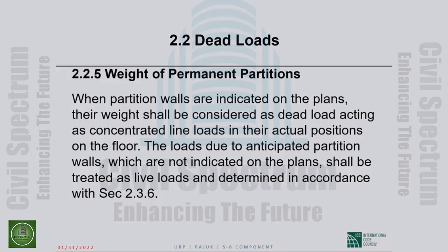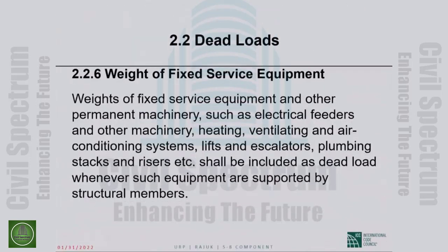The load factor is lower. Movable partitions are live loads, and the load factor on that is higher. A live load factor is what you apply to the weight of movable partitions.